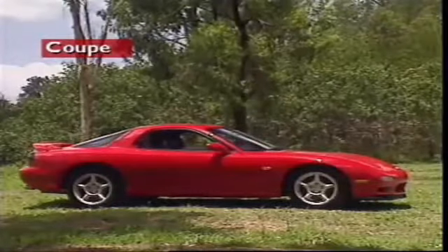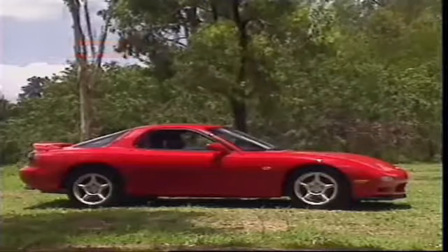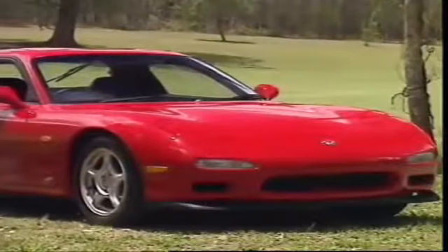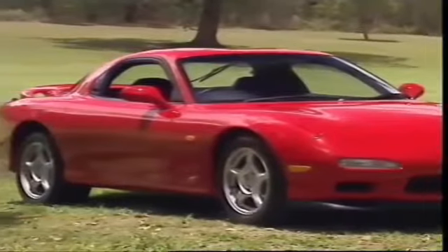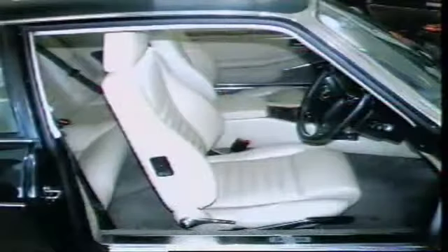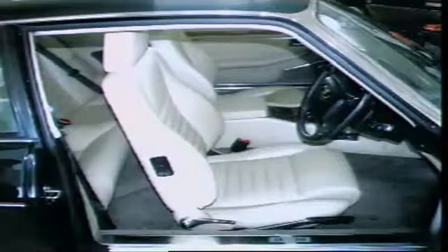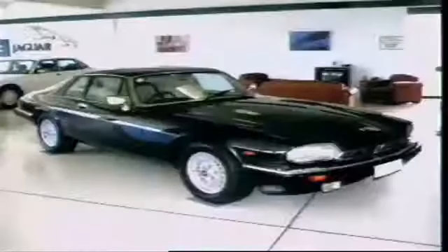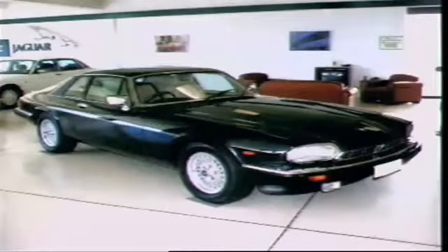A coupe has just 2 doors. Reducing the number of doors to the passenger compartment makes the vehicle structure more rigid. Traditionally, it has 2 seats, with 2 smaller seats behind for occasional use. In this form, it is a close-coupled 4-seater and can be made in a fixed-head or drop-head configuration. A coupe is now regarded as being any fixed-head vehicle with 2 doors.